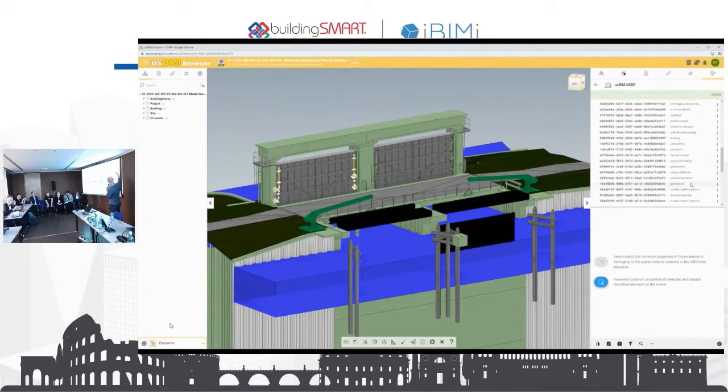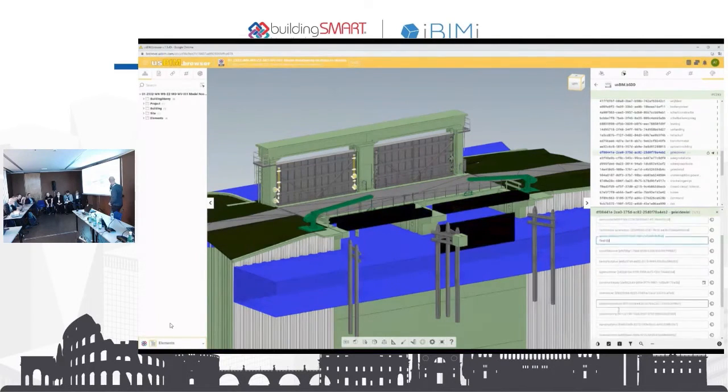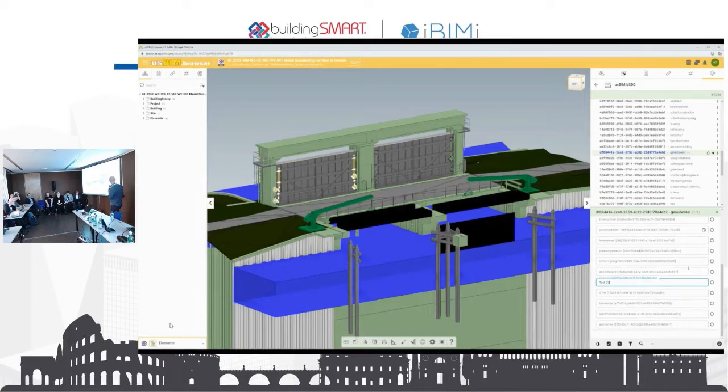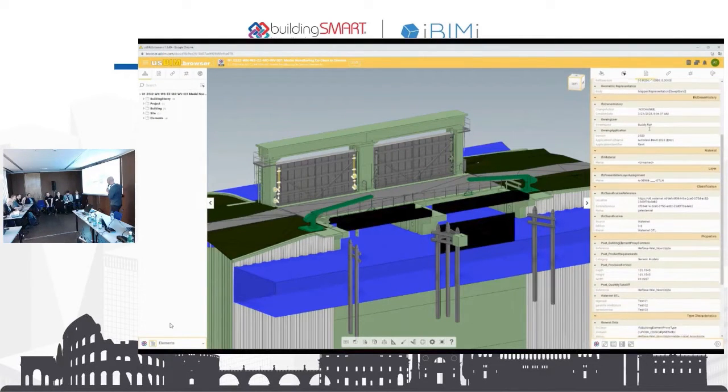In this case, it is a slide wheel, or I don't know the English word. We search for them in the bSDD. We see also a sliding wheel, and we say add to this object, and we get a list of all the properties we need from the OTL. And we give them some values, because only the properties with the values go over. It is added to the IFC. The last one, and now you see added 3 properties. And when we go back to the properties, you see we have added the extra properties that we need.